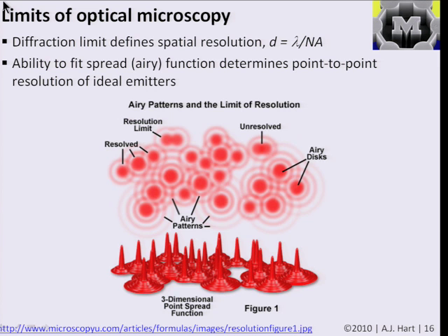So by changing the characteristics of the lens, you can, for example, slightly beat the limit, and that's used in advanced lithography to slightly push this limit down. Another way to look at it is the ability to differentiate between two points. Imagine that you have two points emitting light, as ideal delta functions. They will have a function of emission that looks like that, called an Airy function, and the ability to resolve the location of those two points is the minimum distance that you can measure.